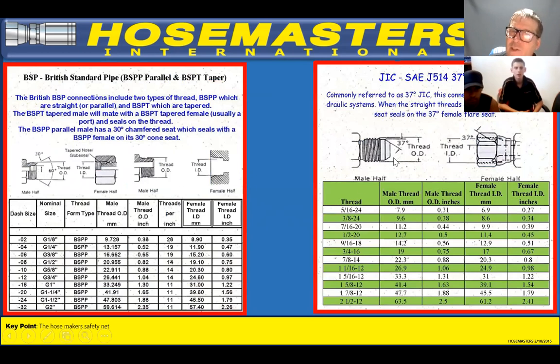But look at JIC. It's going out on the male and in on the female. Can you see that? Yeah. It's the opposite, but this one now is 37 degrees. That seal is 37. That's probably not something you're going to have to worry about too much, but at this stage, I want you to know that's what you're expecting to see when you're looking at it.